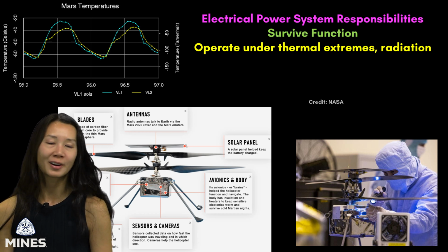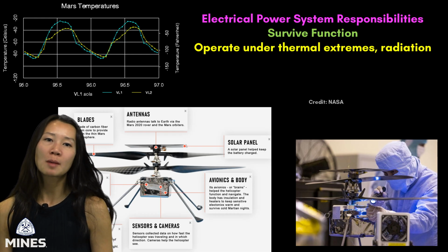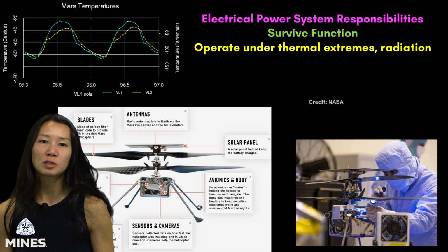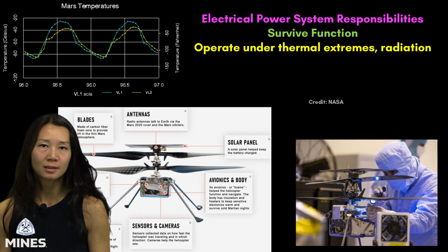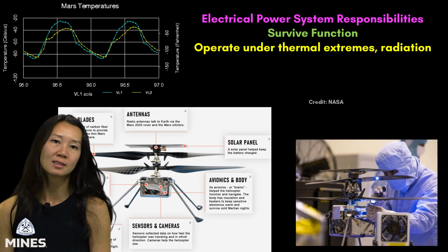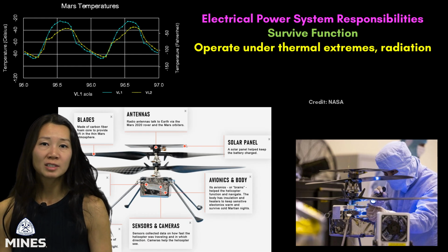US18650 VTC4 lithium-ion cells, kind of like AAs, which have specific temperature constraints of charging between 0 to 50 degrees Celsius and discharging between -20 to 75 degrees Celsius. Storage must be kept between -20 and 45 degrees C.